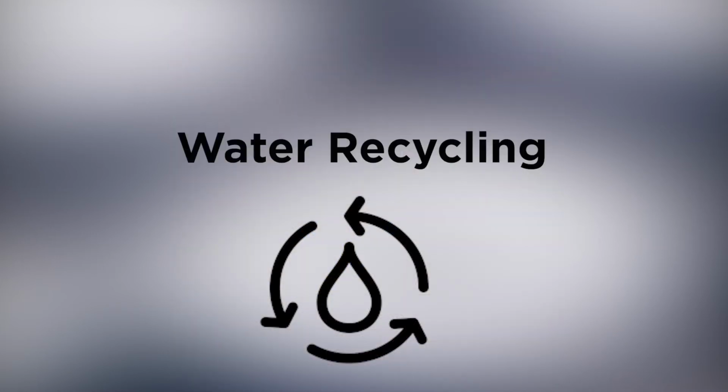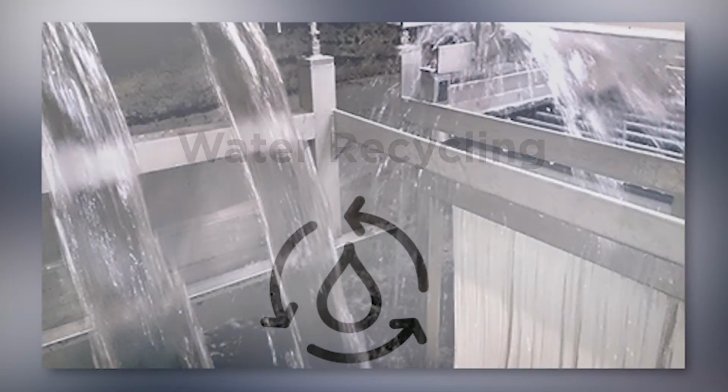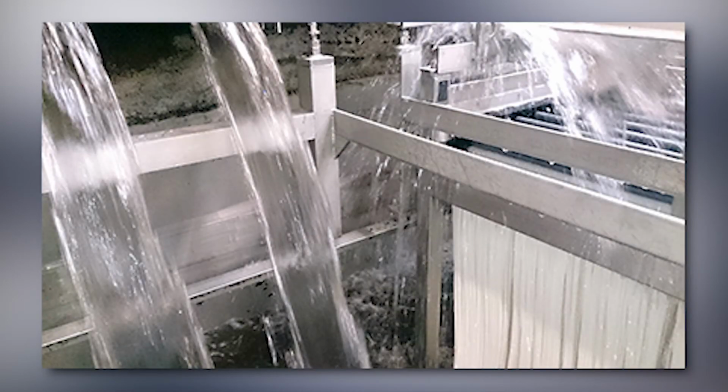The next recommendation is about recycling water. There are sometimes processes that use water and then dispose of it directly afterwards when the water could be recycled and sent to a different process before disposal. Taking a survey of each water stream that goes into the sewer is a good first step. Evaluation of these streams will help determine if water could be rerouted at the end of a process for another purpose. This can drastically lower the amount of water being purchased depending on the situation.